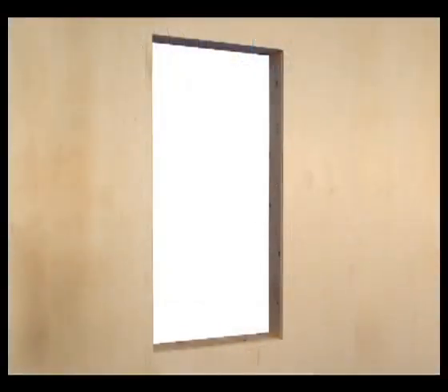This is the window rough opening with 2" by 6" studs and 5/8" sheathing. The window rough opening size should take into consideration the back dam, slope to drain material, and flashing material. Requirements are that the wall and rough opening be structurally sound and not moisture saturated.